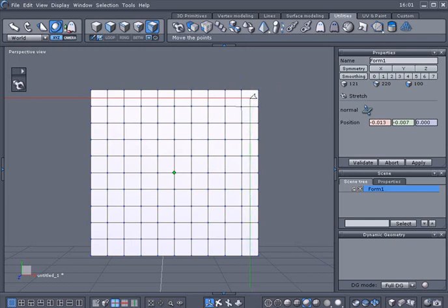We'll set it over here to the right side, and I'm going to click one time. This is going to go ahead and lock it into that position where I can move my cursor now. As you can see, I'm still over in stretch mode. Now the lines I'm talking about were the ruler constraint lines, and you can see them down here in the bottom where my cursor is at. The red and green means no constraint. The red constraint ruler is for the horizontal, and the green one here is for the vertical axes.